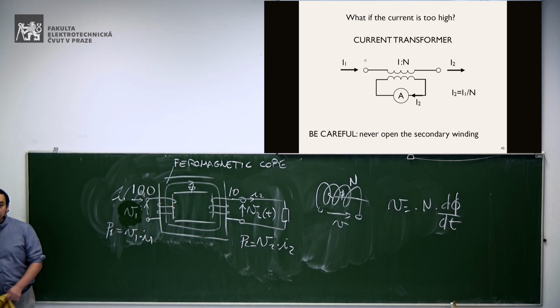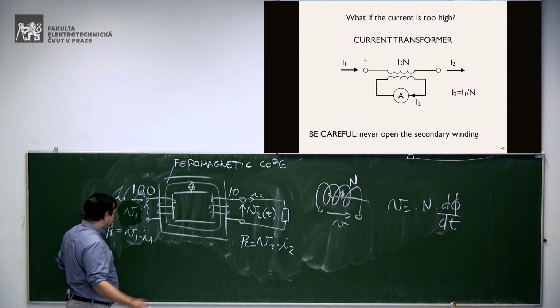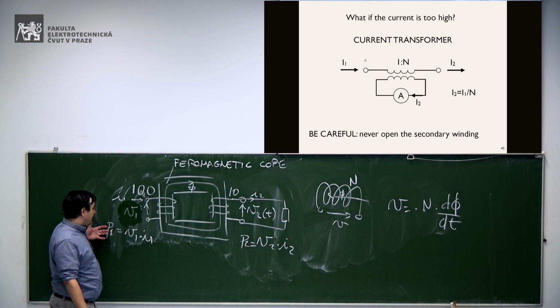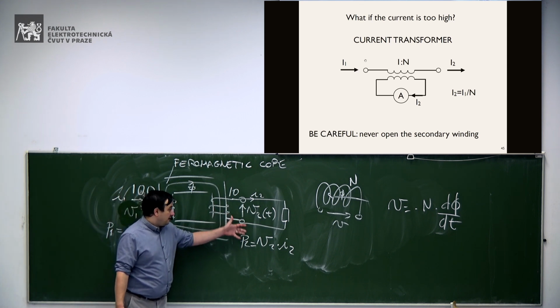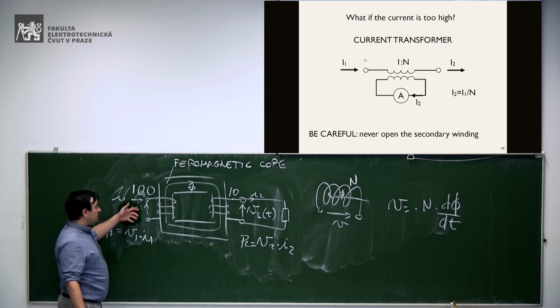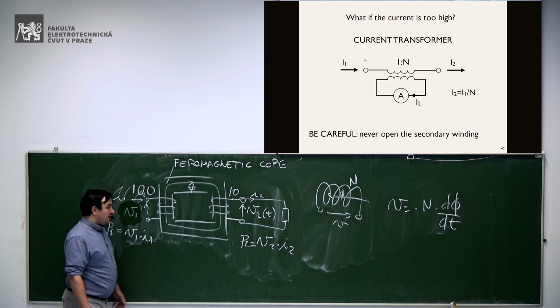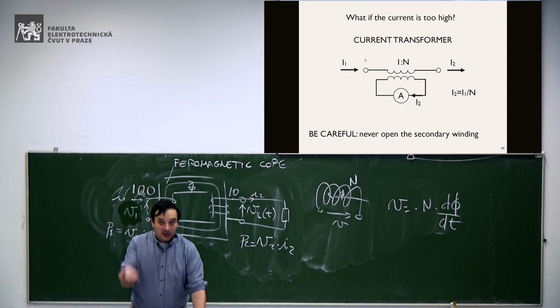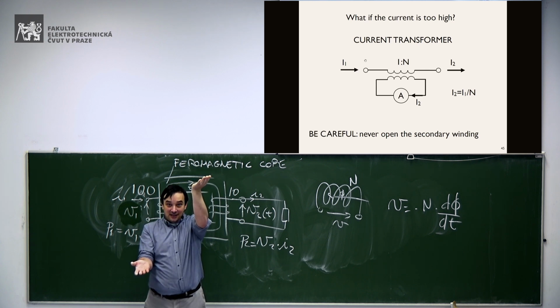Of course, this is not real, because otherwise we would have a perfect machine. There are some losses, but generally speaking, in an ideal case, we will have the same power which enters here, voltage times current, which is equal to the power at the output, voltage times current. Now, if you reduce 10 times the voltage, you increase 10 times the current, okay? The power is always the same, so if you decrease the voltage, to have the same power, you need to increase the current, okay?